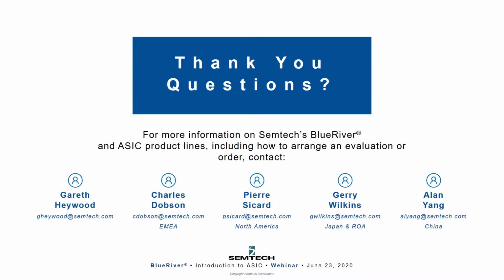Question here, how much DDR is needed around the ASIC? So the DDR is only required when you're using the AV processor. Off the top of my head, I can't remember what the exact requirements are, but that's fully defined in our reference design for you to take a look at. Again, I highly recommend signing up with one of the gentlemen listed here below in your region, and they can provide you all that detailed technical support. But typically, we have two DDR devices hooked up, DDR3, and these are just required, as I said, when you're using the AV processor or you're doing fast switching where you need a frame buffer.